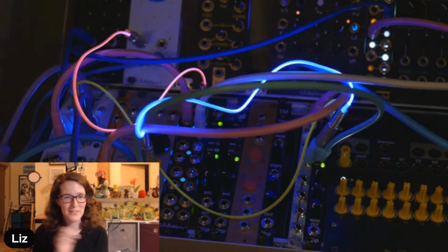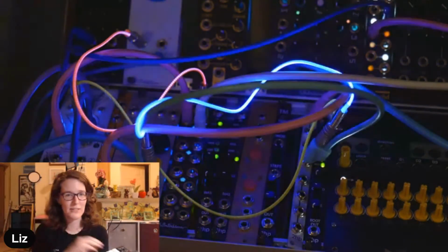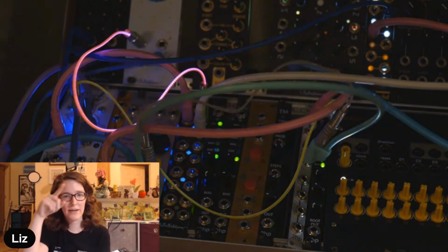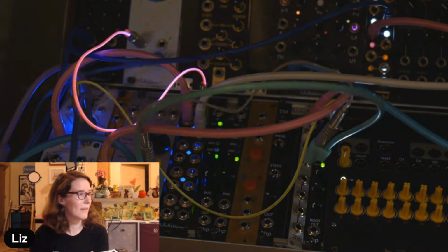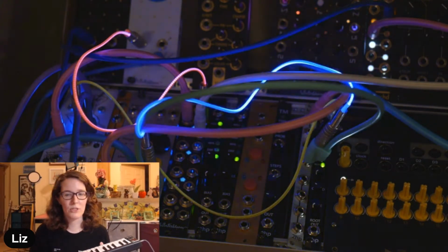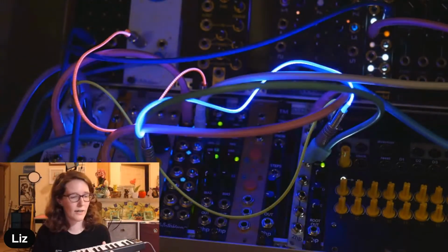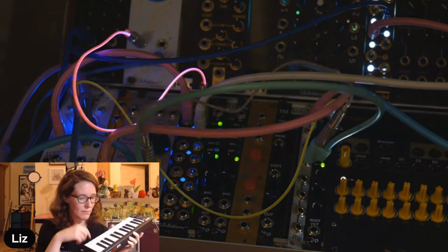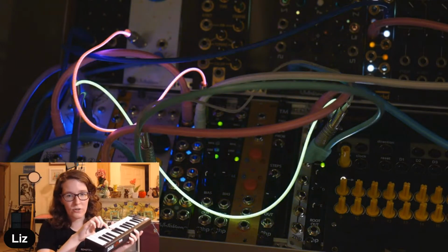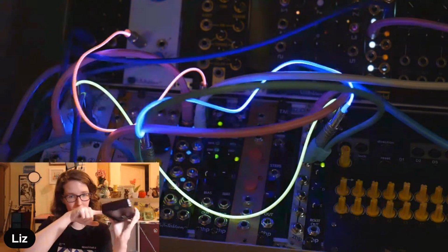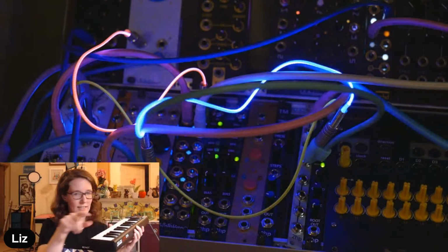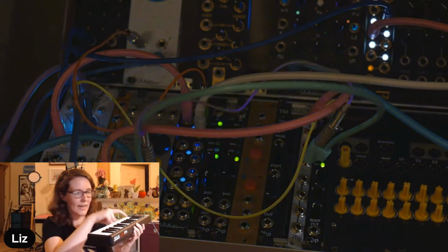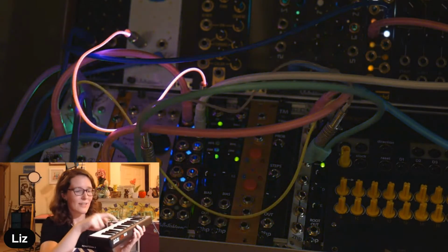So a guide went up this week where I show you how to solder it up to cables, and I've got a little demo going where the blue is getting a sine wave, so you're getting kind of this PWM thing, and then the pink is getting 1V oct, which is how notes are sent to a synth. So it's all different voltages, and I have this keyboard hooked up. So when I press a note, the green goes on. That's the gate signal. While I'm holding down the key, it stays on, and you're going to see the pink change in brightness depending on what note you're playing. Oh, because that's the CV signal itself.